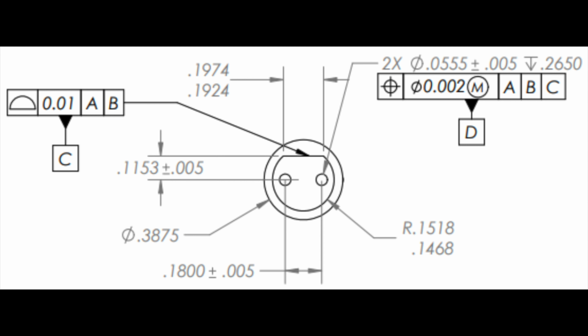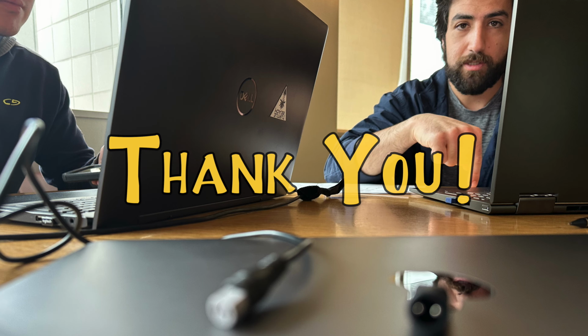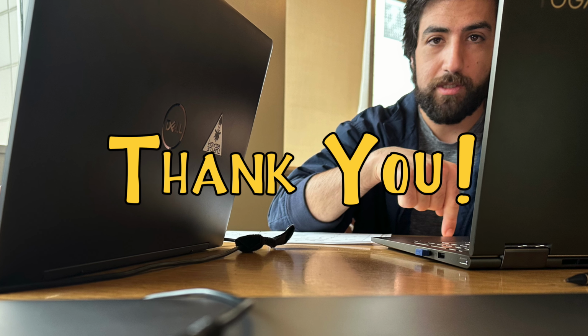We chose to apply a position tolerance that calls for max material conditions. This will ensure the best fit. Since the alignment of the holes and the prongs are essential for the mechanism to work, another tight tolerance of 5 thousandths of an inch is applied to the line located in the datum reference frame C and in the center of the 2 holes' diameters.